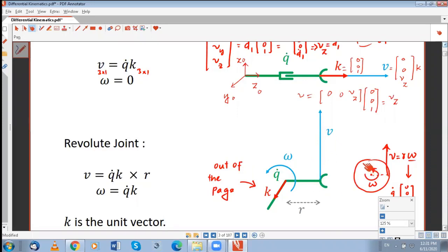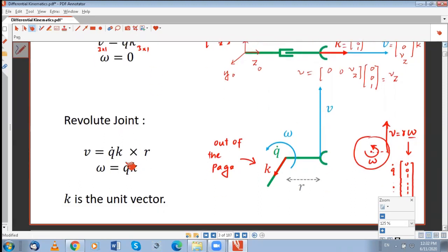Whatever angular velocity this is going through, let's say 1 RPM, the end effector will also move at 1 RPM. But angular motion also contributes to linear motion, because of the tangential velocity formula, r times omega. This was not the case there. So here, q dot is angular motion, it's your omega, and you are getting a linear part and an angular part.